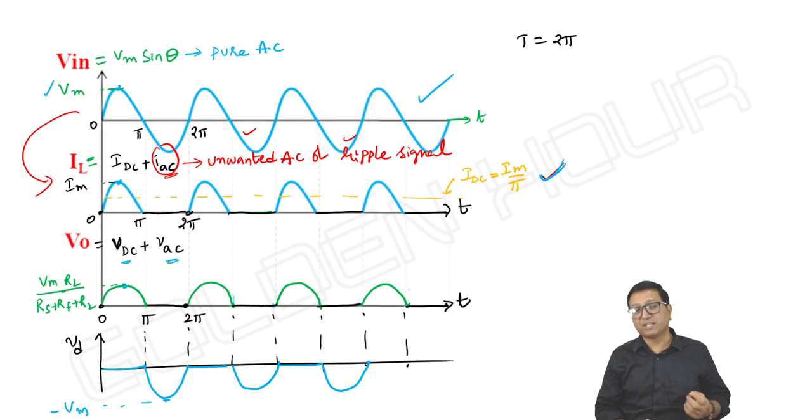If you use a secondary voltage of very large amplitude, then a signal with that large magnitude appears across the diode during negative cycles. That may lead to avalanche breakdown. If avalanche breakdown takes place, the diode starts conducting the negative cycle as well. If the diode conducts, then the average value falls down. The output current as well as voltage become a combination of AC of both positive and negative cycles, which reduces the DC component of the overall result.